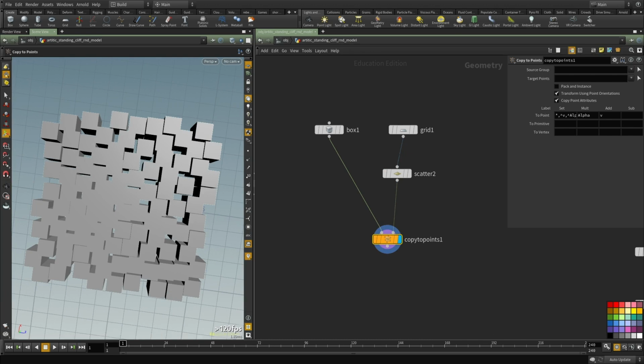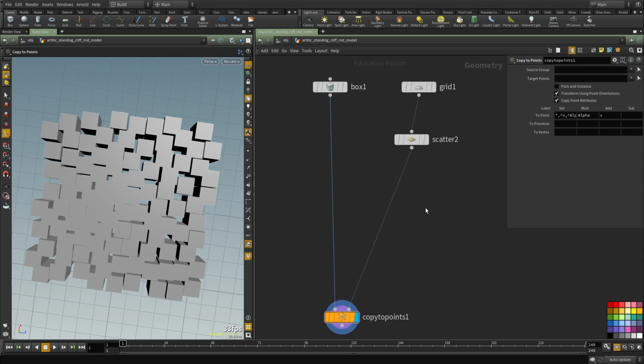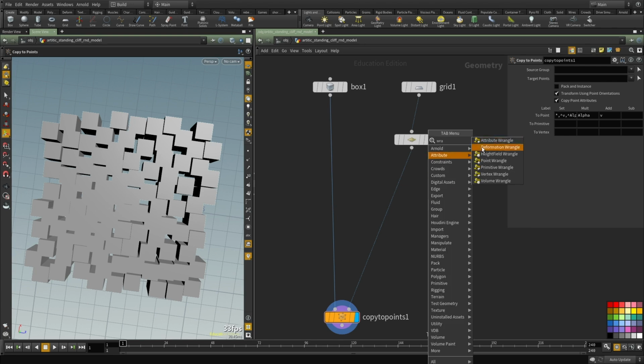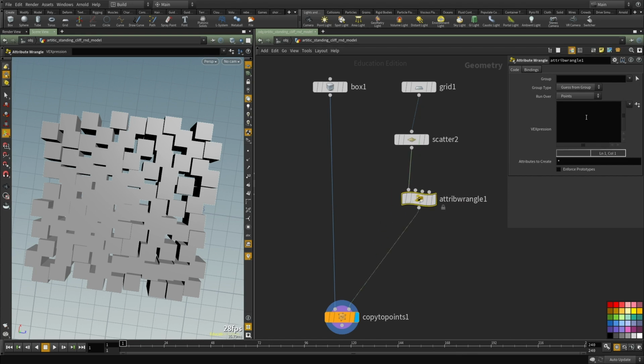We're copying that. Now, in order for us to be able to vary the rotation, scale, and various things, we need to identify a few vectors. The two that are needed are the N and an up vector. So I'm going to use a wrangle attribute, and the syntax is actually very simple. This is nothing to be afraid of. So v@n, this is for the initialize, create an attribute of type vector, and the @ is to create an attribute that is at the point level. The name is this n. So I'm going to give it a value of 0, 0, and 1,